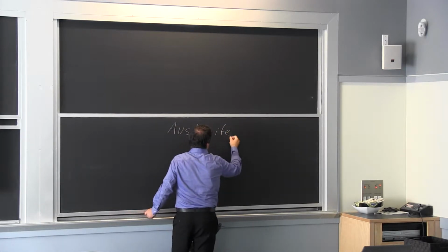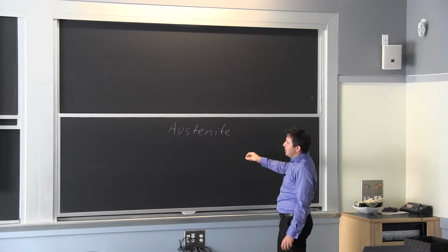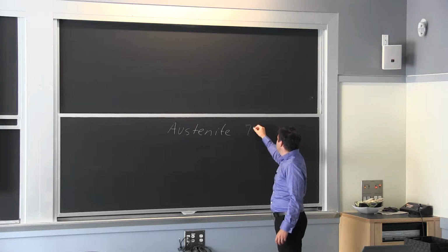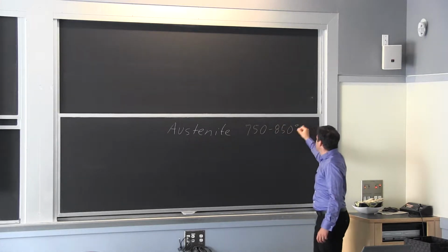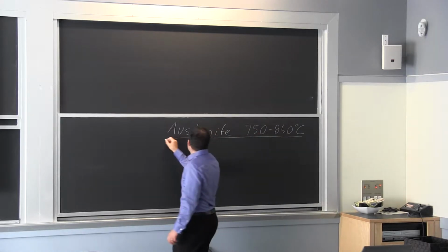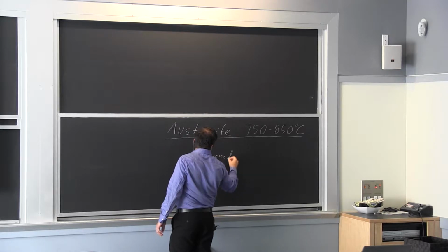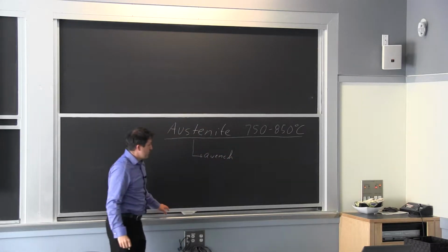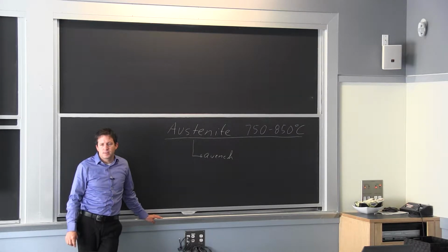and it's stable at relatively high temperature. If you remember the diagram, it's around 750 to 850 centigrade. So that's red steel. So what happens is, first of all, you quench. That brings on a lot of potential distortion. There's a lot going on during the quenching process